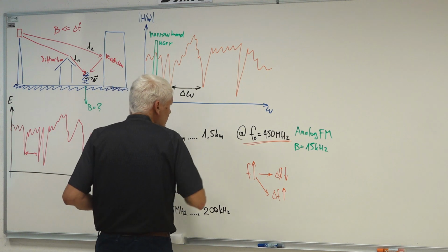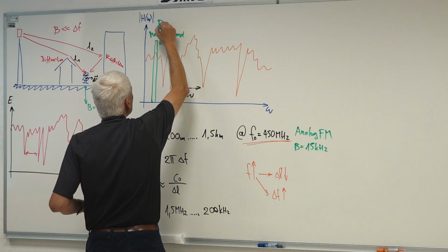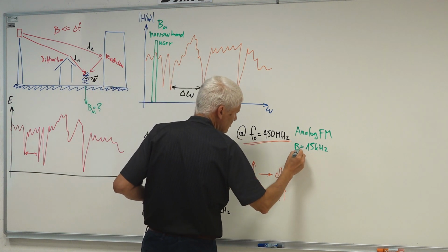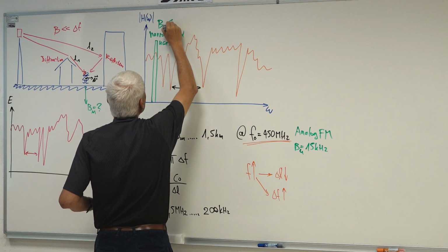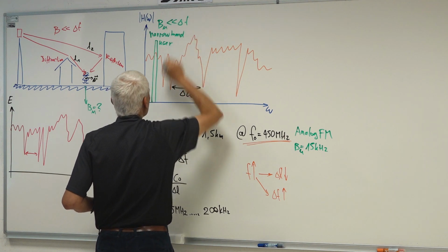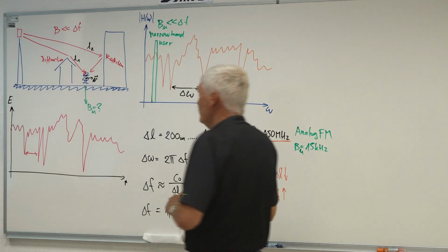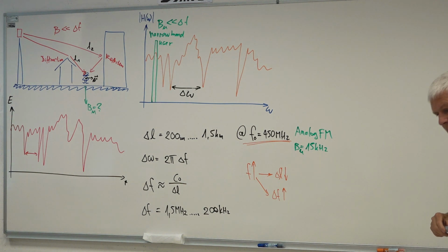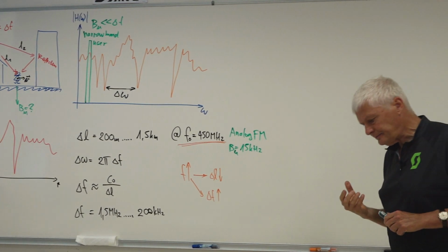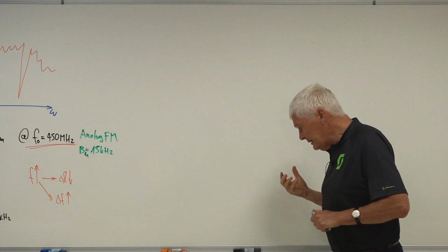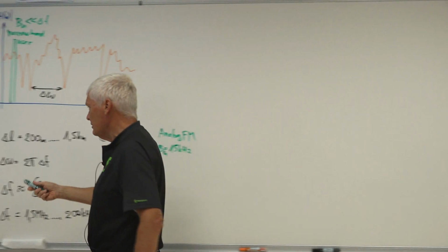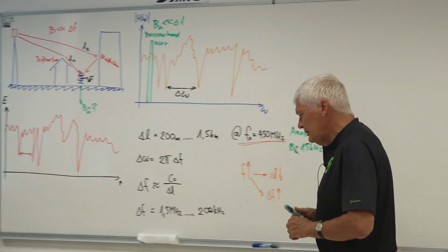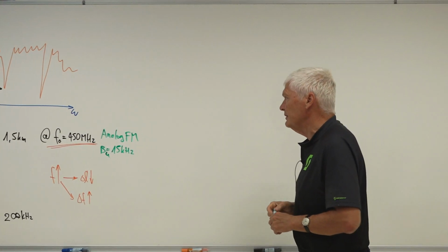A narrowband user will typically have its user bandwidth, if I say BU here, just to stress that it's the user bandwidth, much smaller than delta F. What does the narrowband user see in such an environment? He mainly senses some amplitude change, like here. We're talking about the strength of the signal at the side of the user. He sees amplitude fading, signal fading.